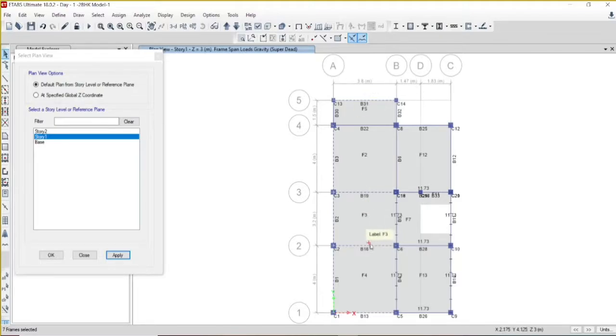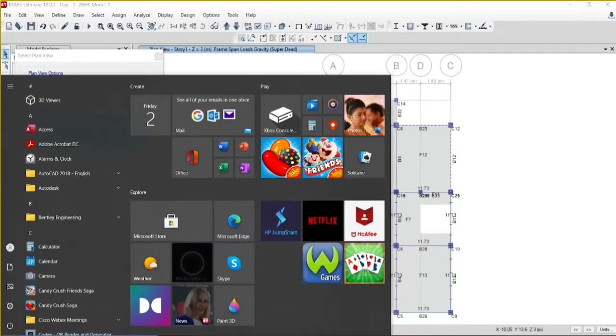In the interior you will not be having the parapet wall, hence you can deselect this. So in all the perimeter you can select. Now these are the areas where you need parapet wall. Okay. Now when applying the parapet wall, it will be a height of 1 meter only.